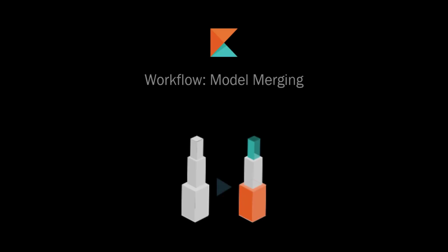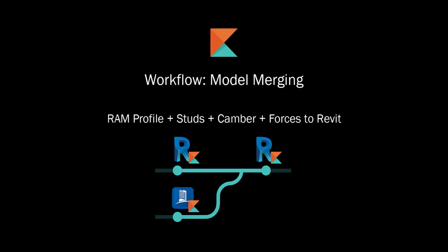Hi, in this Konstru demo, we will look at the model merge workflow. Model merging is a process whereby two building models can be compared via a user-defined geometric tolerance. For objects found to match within the tolerance, data can be transferred between models.